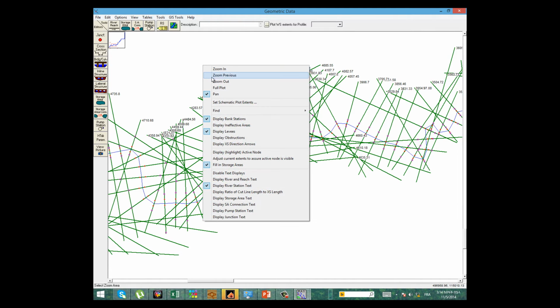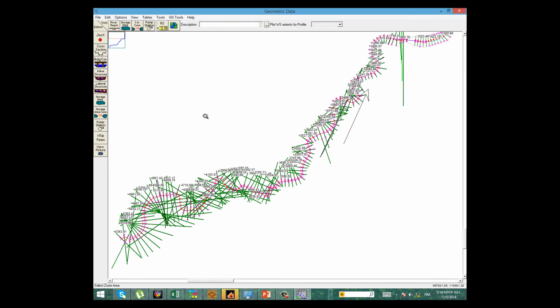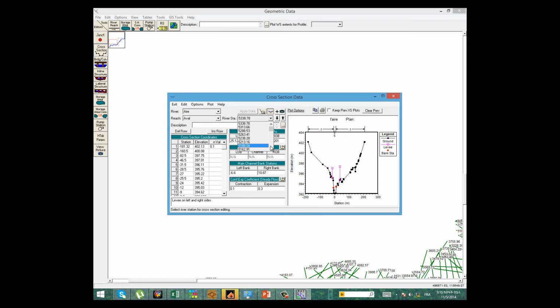So that's all. We can run the software after adjusting each point of each cross section. You can see a lot of cross sections here, around 200 cross sections, so each of them needs to be adjusted: the bank stations, the levees, and so on. Also, in the tunnel it is very difficult to survey, so there is a need for another method of putting many cross sections in the tunnel part.